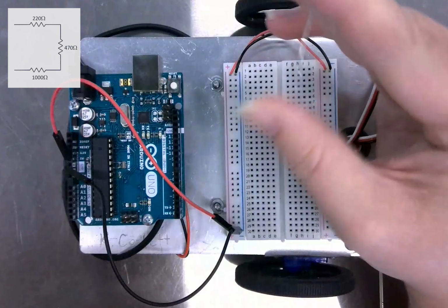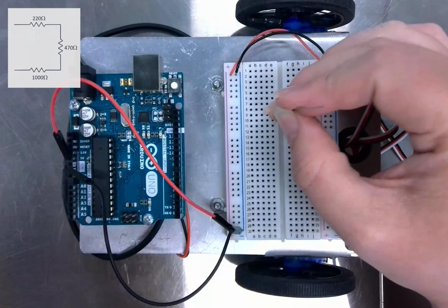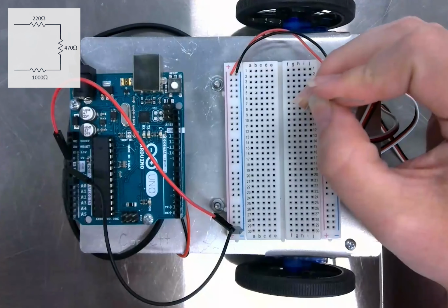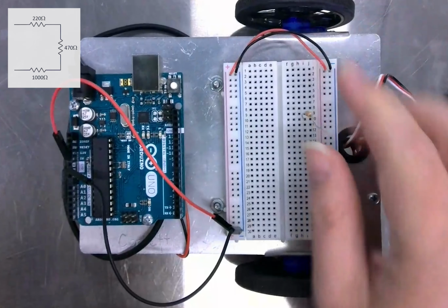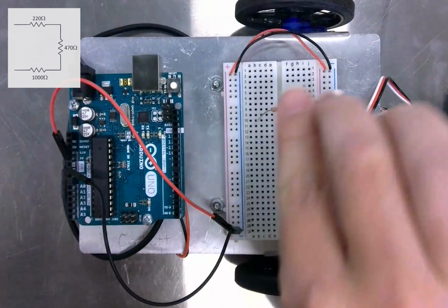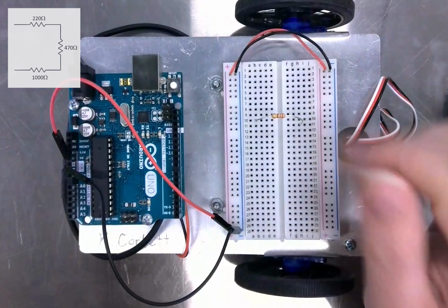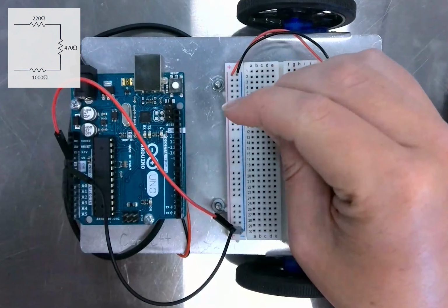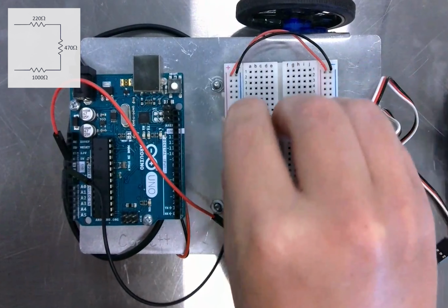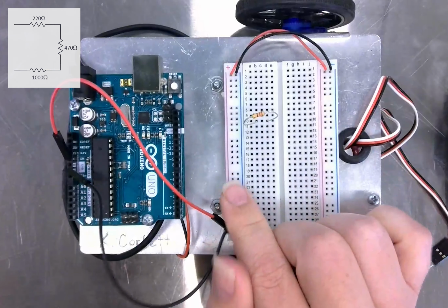And so in order to build that, we need to have the start of the resistor, and you're going to plug it into some row. So you're going to start the resistor and plug it into some row, any row, it doesn't matter, and then you're going to plug the other end of the resistor into some other row. Don't plug it into the same row. If you plug it into the same row, imagine if we did have it connected to power. Then this whole row is connected. Current will just go straight through that row, and it won't ever go through that resistor.